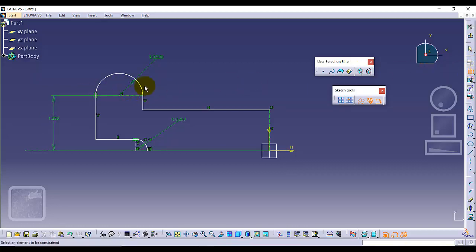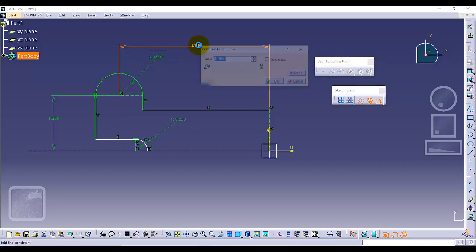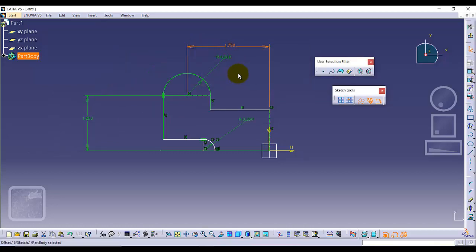And again I am going to select dimension, select this point and this axis, and this dimension I am going to add 3.5 divided by 2. Again you need to observe the drawing, and you will know why I divided 3.5 over 2, because I am making a quarter sketch, and then I am going to mirror it with this reference and with this reference.